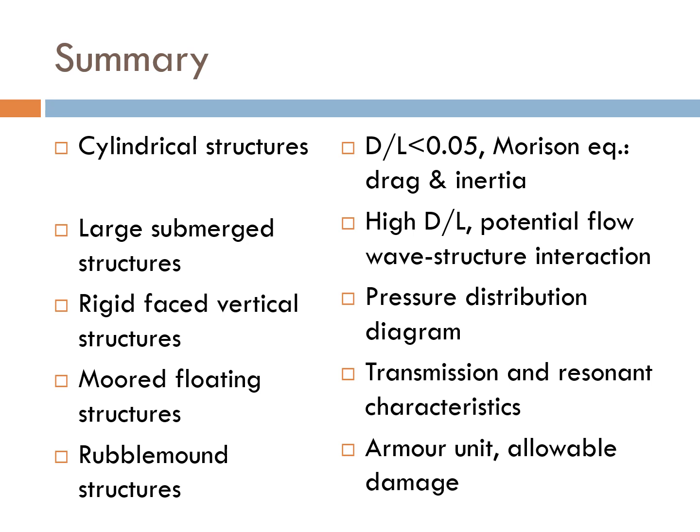By now, we have completed our study on the design principles of the different types of coastal structures. To summarize, for cylindrical structures where the dimension of the structure is much smaller than the wavelength, the Morison equation can be applied where we evaluate both the drag and also the inertial component of the forces acting on the structures.